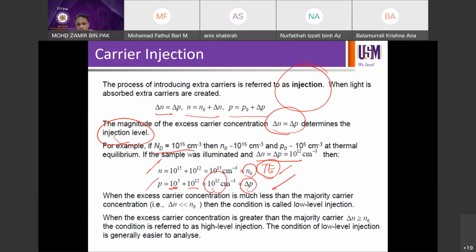Okay, so as discussed on the previous page and on this page as well, you can see that if your injection level is way lower than your original concentration of the majority carriers, it barely changes. It wouldn't change the majority carriers, but it will only change the minority carriers, right? But that depends, of course, right?